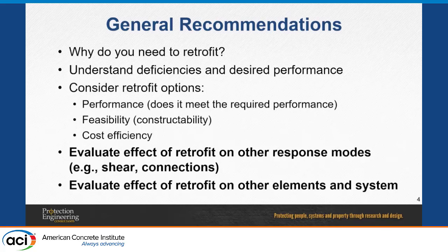But then there's also evaluation of the effect of the retrofits on other elements, looking more at the structural system. Because you're changing the stiffness, potentially, depending on the type of retrofit, you're changing the capacity, which may cause some load redistribution. For some of these retrofits, not all, you're maybe increasing the weight.